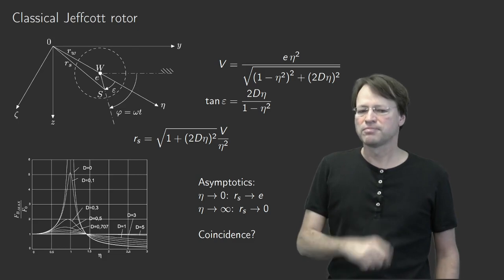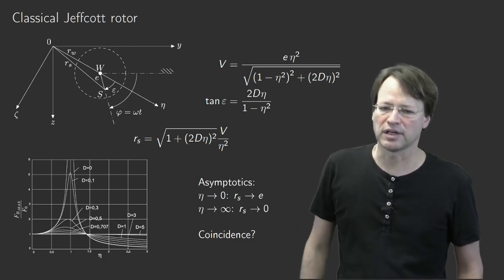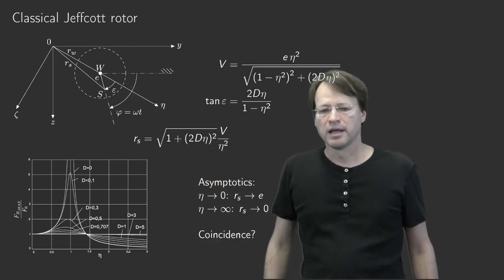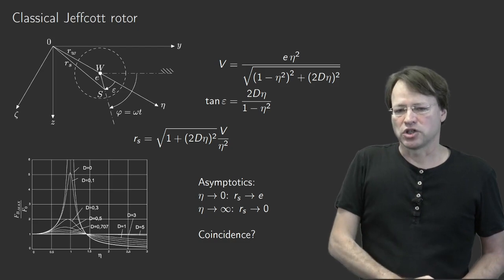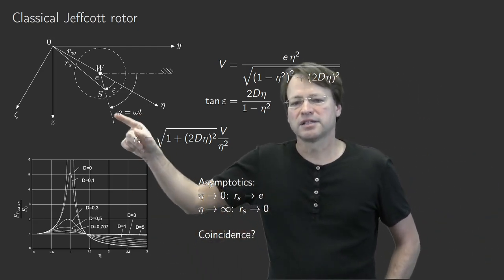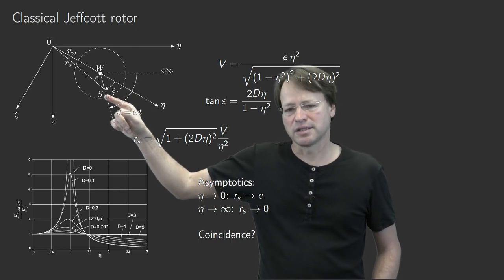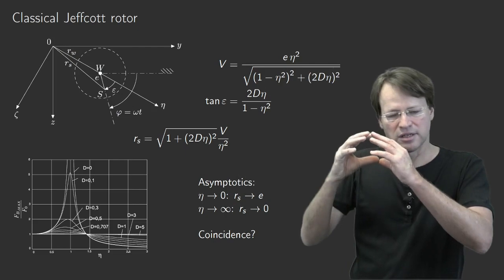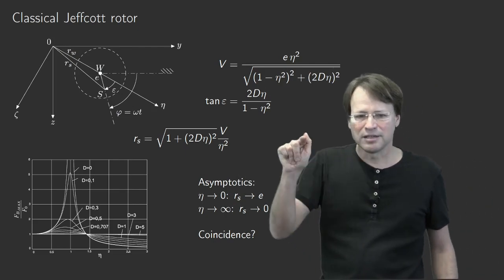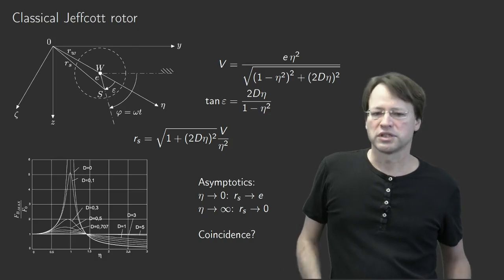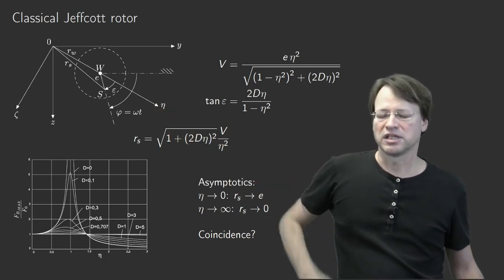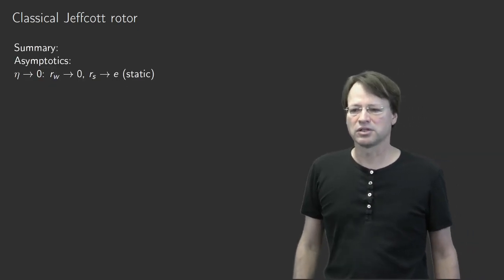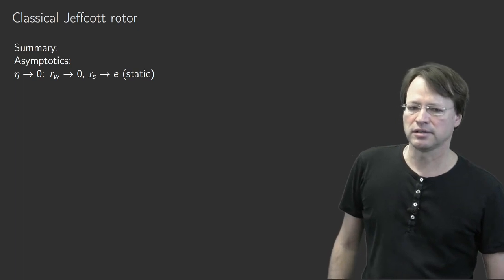And this effect for high-speed rotors is called the self-centering effect. So a Jeffcott rotor with this imbalance here, under high-speed operation, leads to a self-centered rotor in the sense that the center of gravity moves to the theoretical center, to that ideal line that connects the two centers of the bearings to the center of my inertia system. Yeah? So this is very important, and this is what we have to retain as a summary.